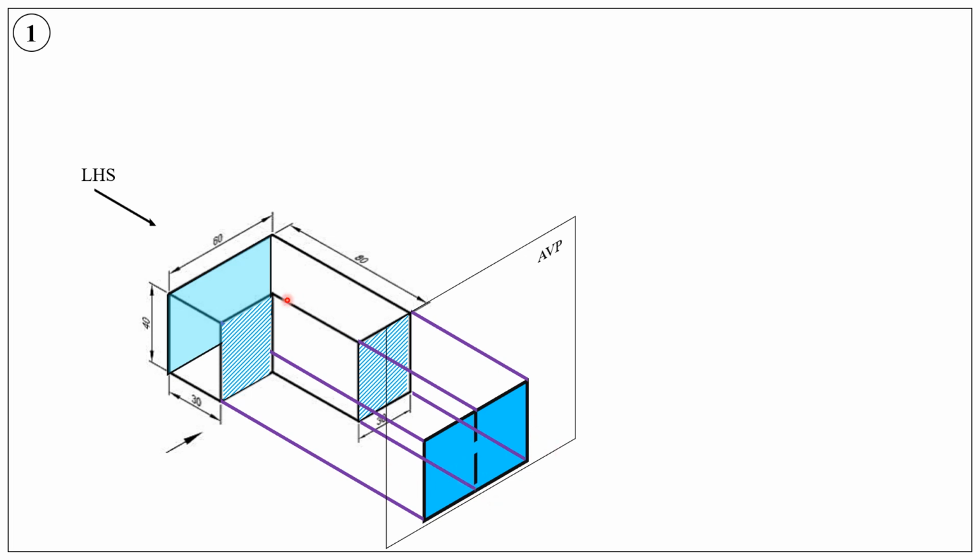Already we discussed this left hand side view is a combination of these two sectioned rectangles. So in order to represent the line of intersection between these two rectangles, we used a dotted line because the line of intersection is hidden by this surface when you look from the left hand side. So this is the required left hand side view.